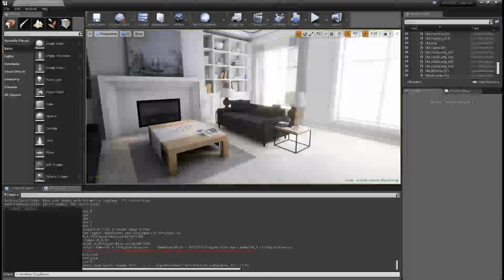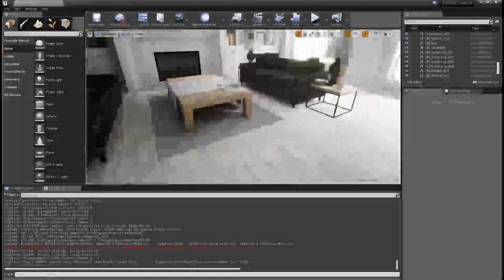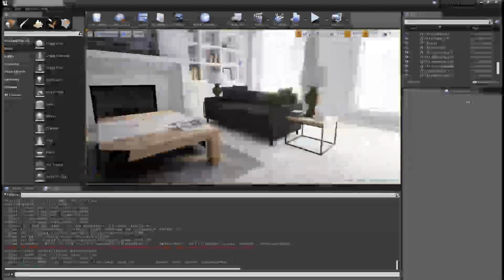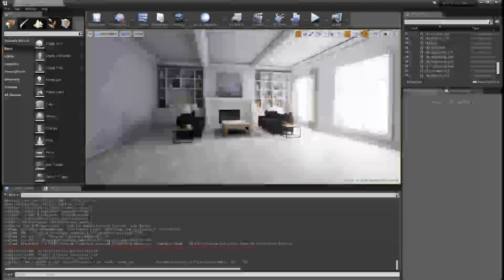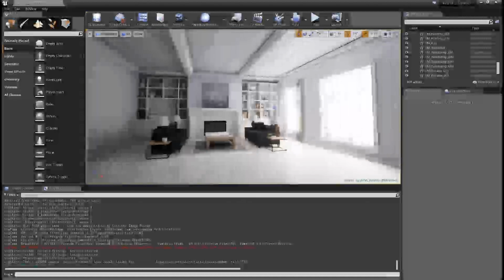So for instance, I'm going to go ahead and set it to 100. And we can see here how it's clipping out very close to me. And that looks, obviously, that's undesirable. We don't want that. But if we were really far away, we wouldn't notice it. And that could help improve our Z-fighting problems.